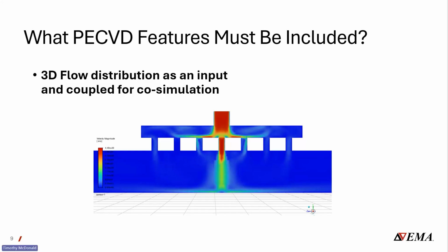Next, we want to think about localized heating that alters the chemistry and flow. Heaters and the RF power absorption or hotspots can create temperature gradients. So the gas temperature affects reaction rates, the Arrhenius dependence, and the gas density. Hot gas is less dense, altering flow patterns. It also affects the diffusion rates of radicals and byproducts.